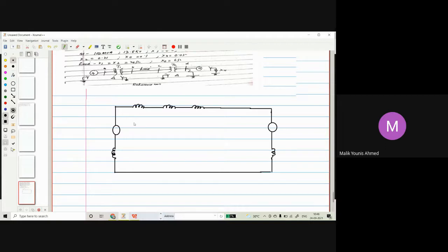So I will be writing the values. This will be a plus-minus voltage source, generator 1, plus-minus EM, whatever the name, EM motor. Then for transformer 1 positive sequence 0.1, and for the transmission line 0.105, all in per unit, and then for transformer 2, 0.1.